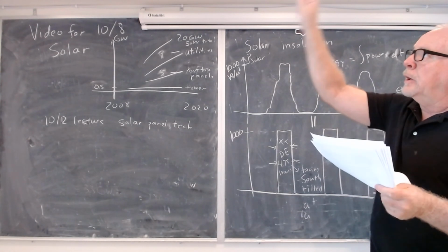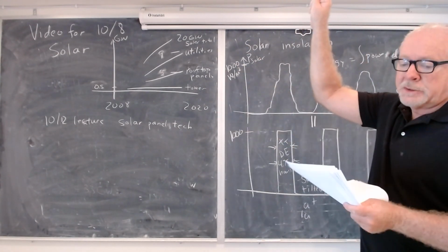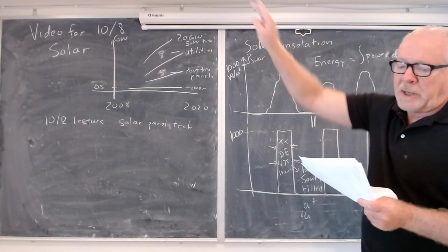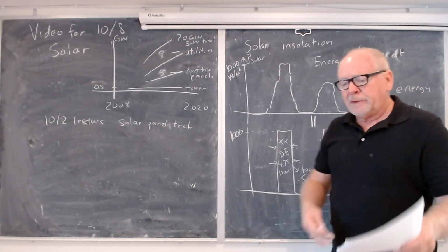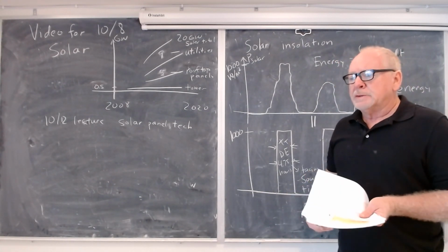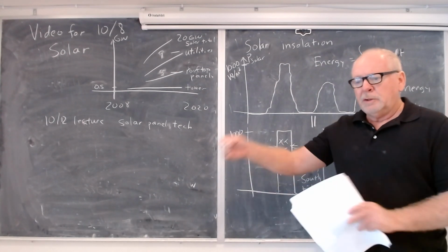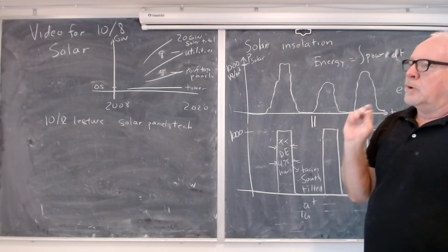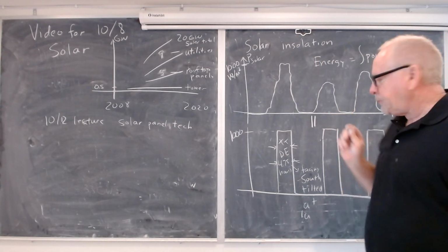So that as the sun rose in the summer and went higher in the sky and lower in the sky, you got that best average. Basically, tilted at latitude means, and you can figure out the geometry here, that at the equinoxes, September, March, the sun's rays are exactly perpendicular to the panel.